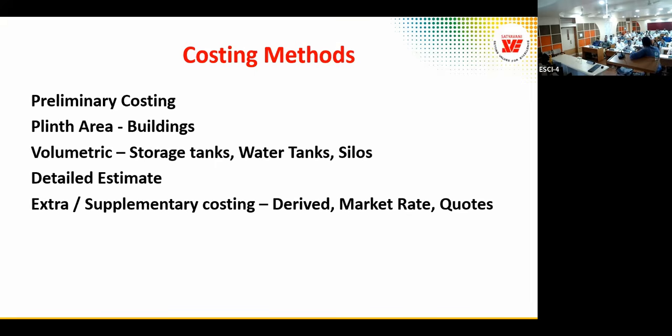Then I use the M30 rate and take the design mix of M30, M25 and M40 and see the variation in the cement and other admixtures, and add the additional cost of cement and admixtures. That is the derived rate. If there is a totally new item, then you should go for market rate analysis and also market quotations.